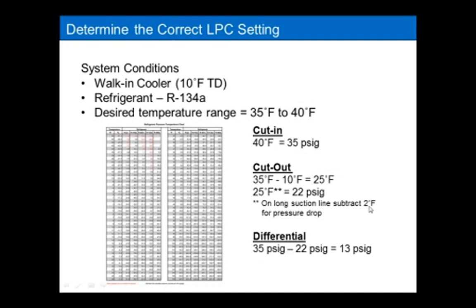Now notice I was talking in terms of temperature, not necessarily pressure drop in terms of pounds per square inch. Most piping charts and piping manuals, when they talk about pressure drop, use the term change in saturation temperature, and they use this change as the measurement of pressure drop. It equates to actual pressure, and we'll show you how that comes to be in a second, but the manuals sometimes call out the 2-degree change in saturation temperature as the guideline.